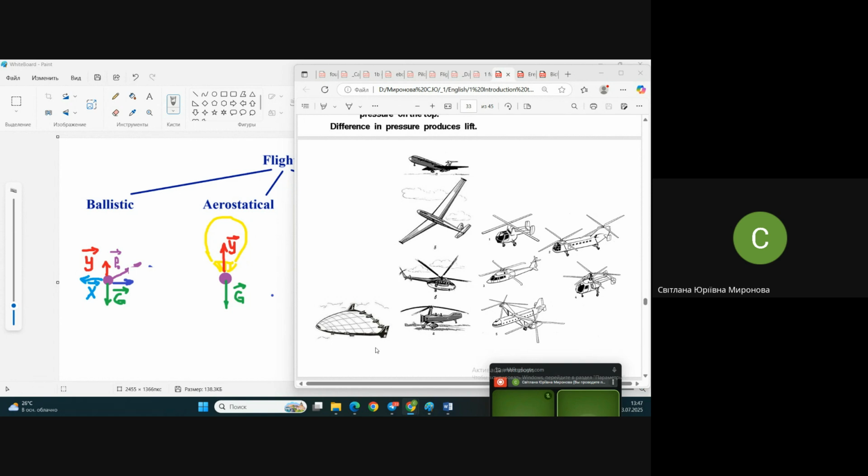At higher heights, they just lose the additional bonuses from the ground effect. What does flat surface mean? It may be a desert, a polar area, or a sea surface, for instance. And in this case, such a flying machine is extremely effective, much more effective than an airplane, for instance. I'm talking about the coefficient ratio of payload to the whole weight of the aircraft.